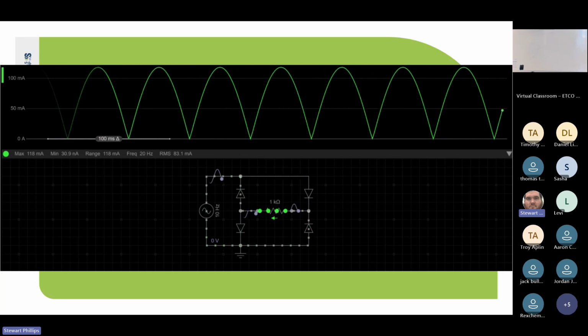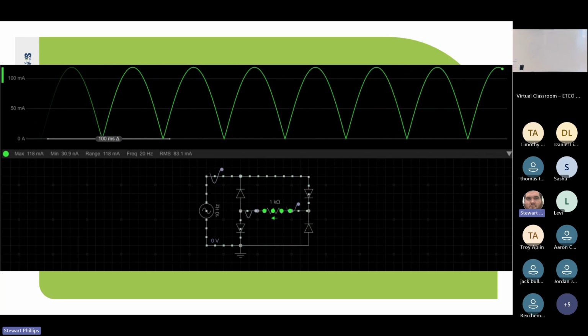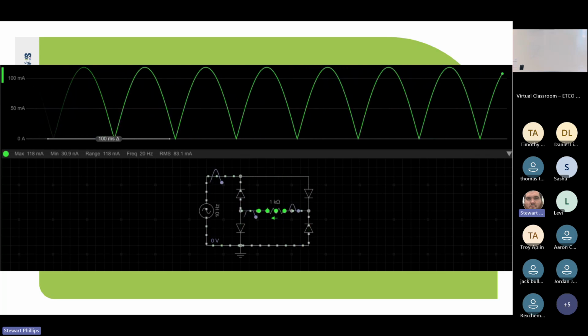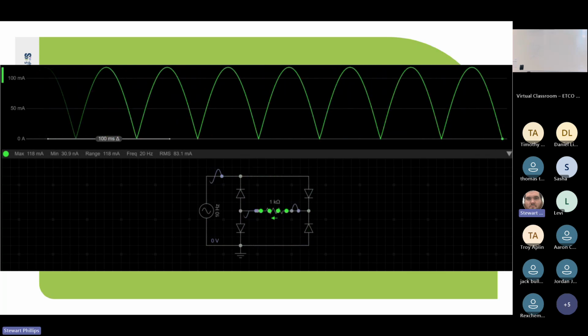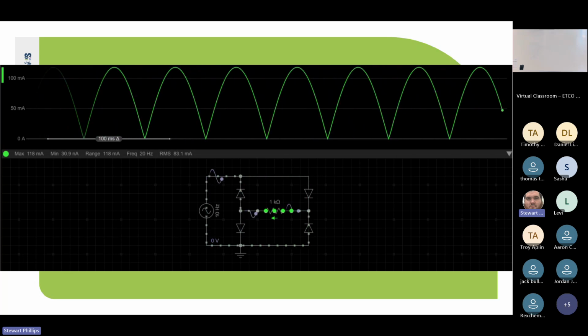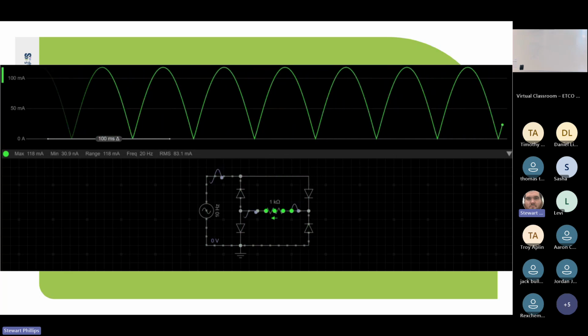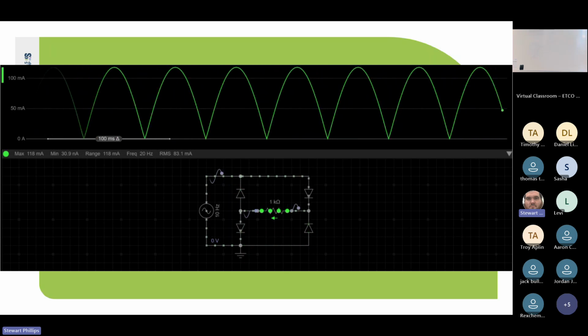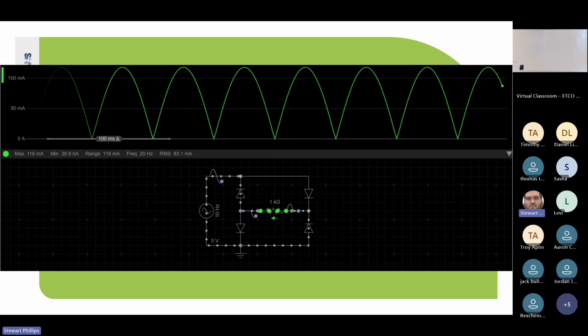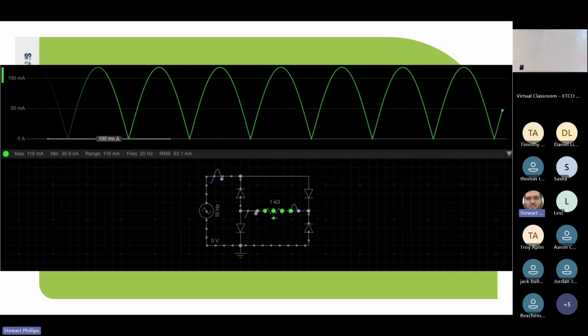In the bridge, we've built clever plumbing so water always flows in the same direction, no matter which way the pump turns. It's still pulsating DC, but now we're using the full AC waveform, which again would be fine if you're just charging a battery, but it's not going to be any good for using any kind of electronics. So then we need to add